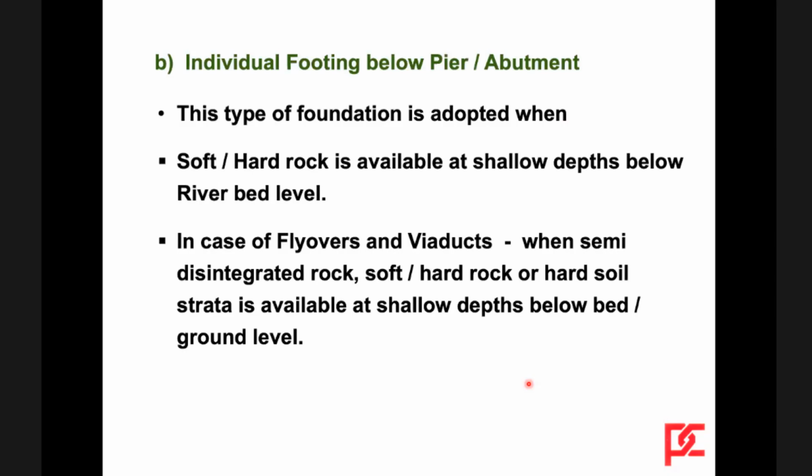Then individual foundation for pier or abutment. These individual foundations are adopted when soft or hard rock is available at shallow depths below river bed level. In case of flyovers and viaducts, when semi-disintegrated rock, soft or hard rocks or hard soil strata is available at shallow depth below bed, ground, etc.